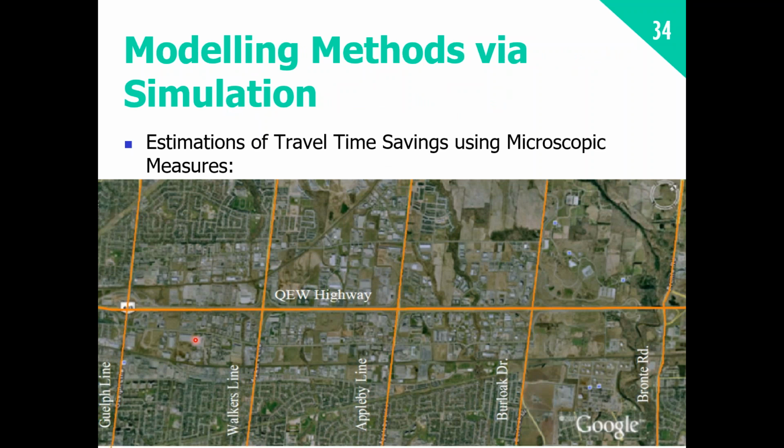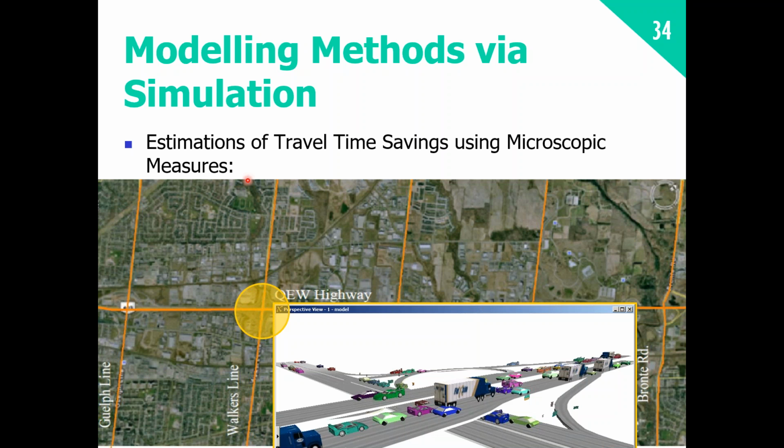Okay, what we have talked about so far is the modeling approach using macroscopic measures such as speed and traffic volume. However, the macroscopic impact on traffic flow as a result of inclement weather events is triggered by individual driver behavior changes. This so-called microscopic driver behavior is also dictated by different microscopic traffic parameters, including car following behavior, lane changing behavior, gap acceptance, acceleration, decelerations, etc. There has been limited study conducted in the past dedicated to modeling driver behavior, mainly due to the complexity of human behavior and the difficulty in gathering microscopic data, so we'll talk about how this can be done using a simulation approach.